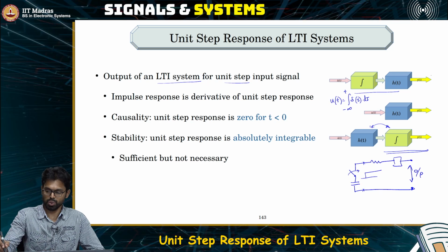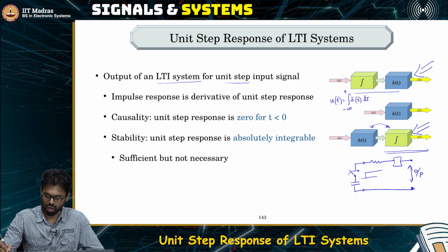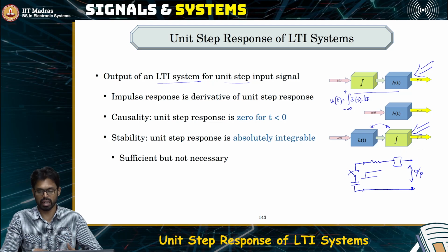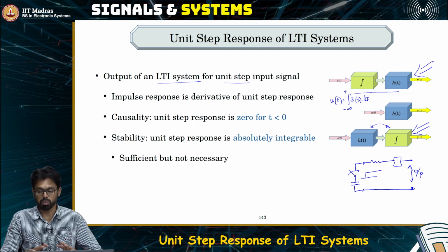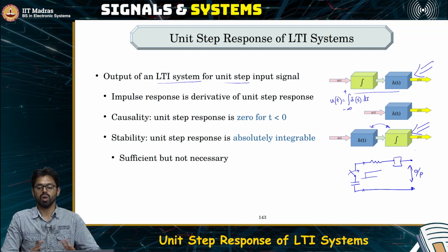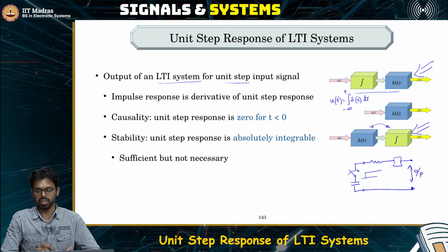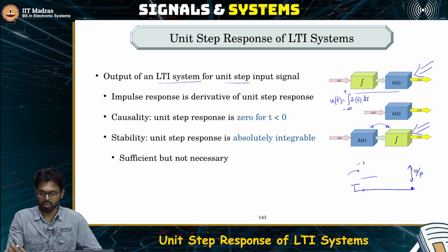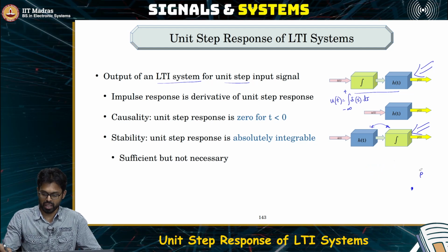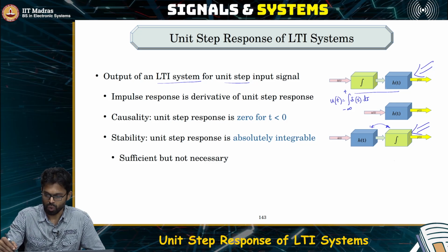These two systems, this one and this one, are equivalent because both are LTI and the outputs are bounded. As long as the outputs are bounded, you can change the order of the systems you are cascading as long as each of the individual systems is LTI. We know that the individual systems are LTI, so the order does not matter. So what do we have here?